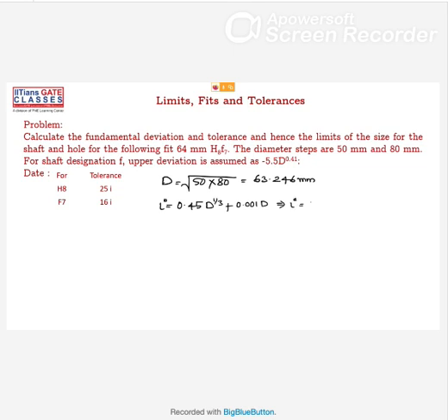That is I is equal to 0.45 into 63.246 to the power of 1 by 3, plus 0.001 into 63.246. So you can calculate I. What is the value of I here? Anyone, in microns? Okay, tell me in microns. 1.856 microns, okay, 1.856 micrometers. Then you can convert this into mm.